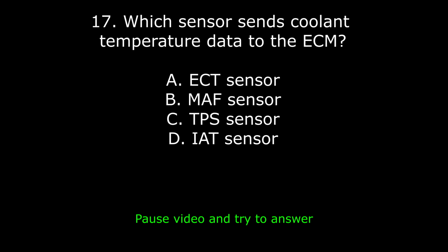30. A customer complains of weak heater output. Possible cause: A. Thermostat stuck open. B. Low coolant. C. Clogged heater core. D. Any of the above. Answer: D. Any of the above. Explanation: all can prevent hot coolant from properly flowing through heater core.